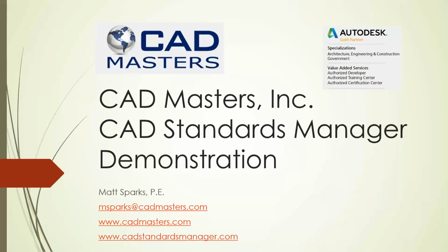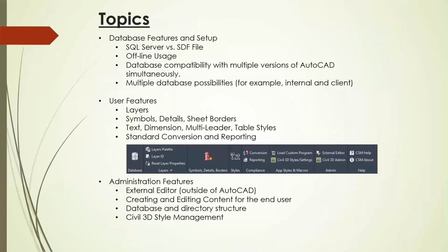What I'd like to start with, since we're talking about the AutoCAD side as well as the administration side, is that we have two pieces of software: one the user uses, and one the administrator can use to add and edit content. We store our standards in a database. We can either use SQL Server or an SDF file.